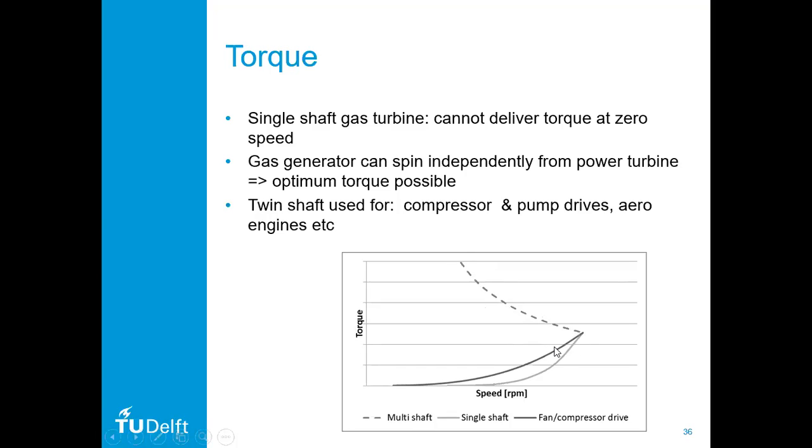And there, of course, you have that split between the gas generator and the power turbine. You can really see that for non-constant speed drive, for example, fans or in aero engines, pump drive, you normally use those twin shafts. For constant speed drive, for example, generator shaft drive to supply the electrical kit, you can apply both. For the big ones, normally heavy duty, the single shafts are more applicable, but you can also use a dual shaft in that. So there are some possibilities.